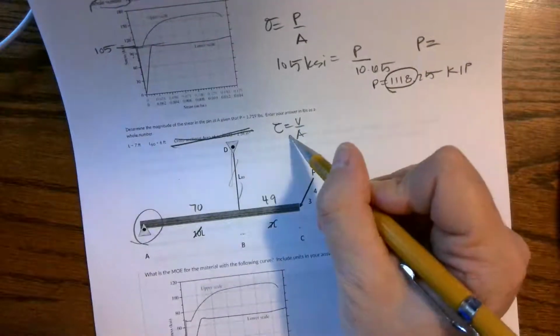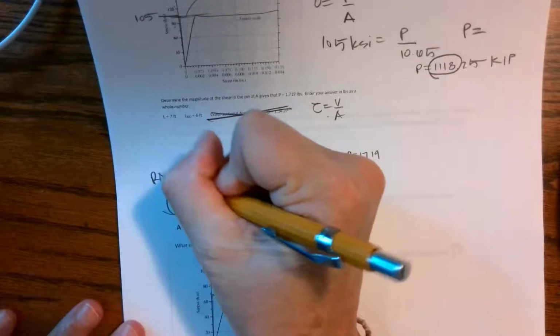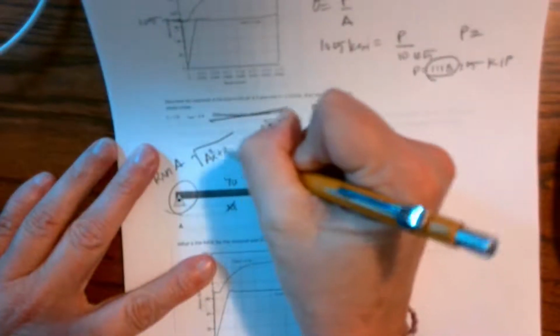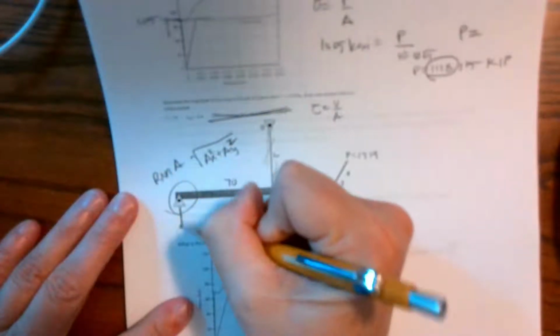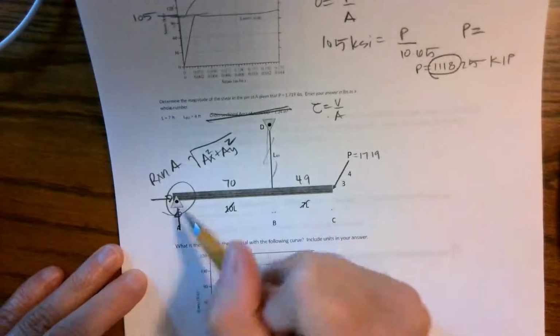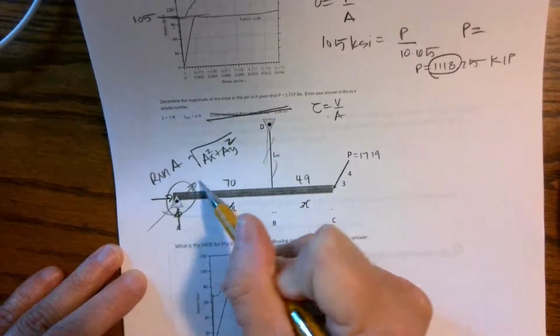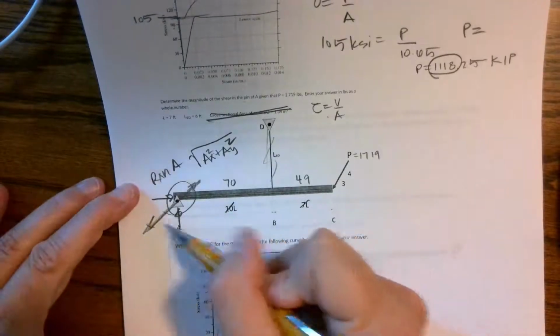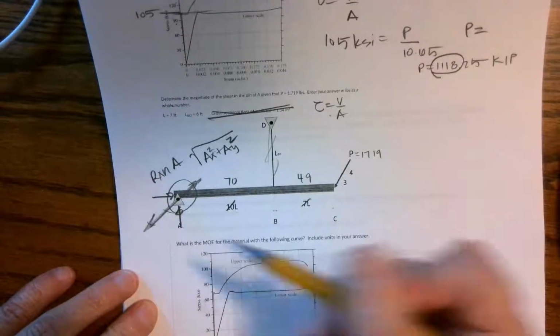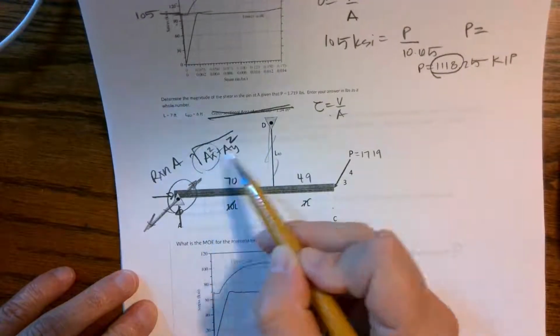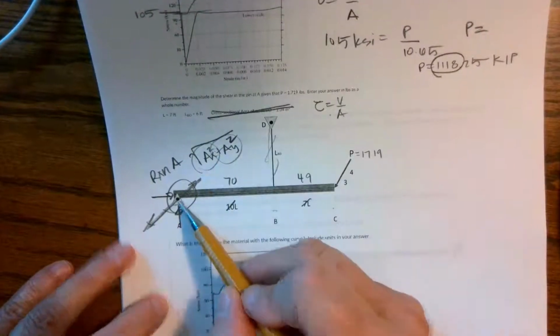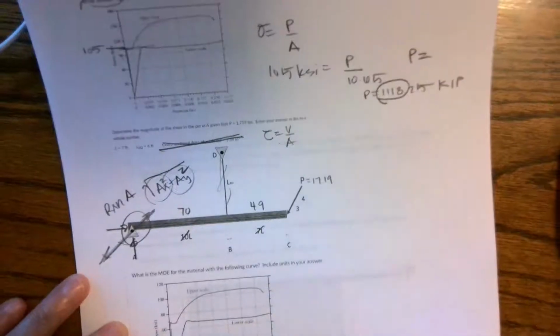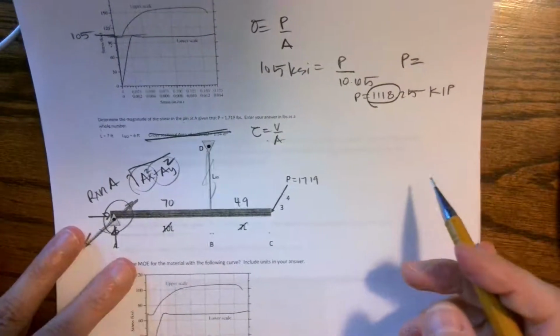So the shear is going to be my reaction at A. It's going to be the square root of the x component and the y component, because we end up with an x and we end up with a y. But actually, the resultant, okay, we're actually pulling back in the direction that is the combination of x and y. So I need to find ax, I need to find ay, then I can take the magnitude, okay, and that's how I would design a shear pin.